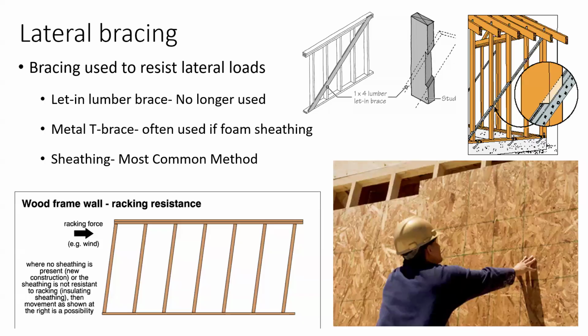Okay. So when I was starting, energy was very expensive. Everybody was using foam sheathing. Now I see a lot of fully sheeted plywood or OSB houses. So it's kind of gone back from what it was when I started my career. Now, the perfect wall for energy is to have foam sheathing because it's a continuous layer of insulation. It's like a layer of fat on the outside of the structure that keeps the structure warm.